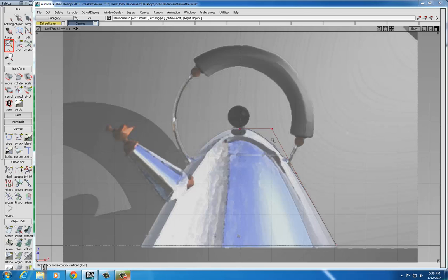One additional thing to notice when you're placing these CVs is how the icons for each of the CVs are represented differently. The first point is a box, the second point is a U, then the third, fourth, and any points you place after that are all shaped like the letter X. The U is there for a couple of reasons, but ideally it helps you to identify the direction of the curve. So you can tell whether it's going one way or the other. Now, in this case, it doesn't matter because we know where we started and finished our line. But if we were to create a circle, as we'll do here in a couple of minutes, you'll be able to tell why it's important to tell where the second point is on there.